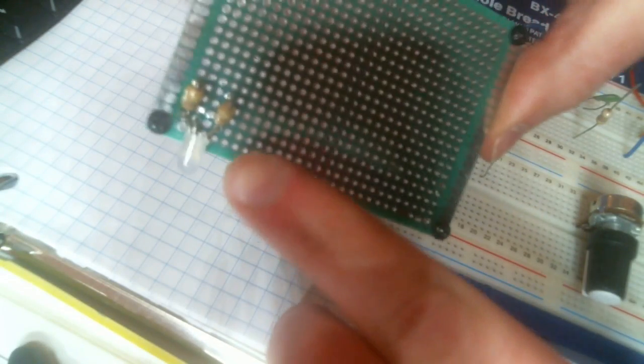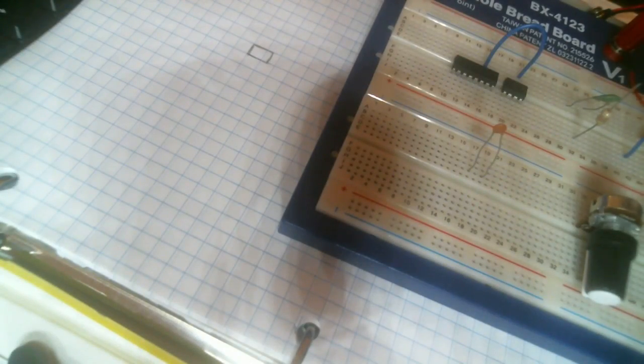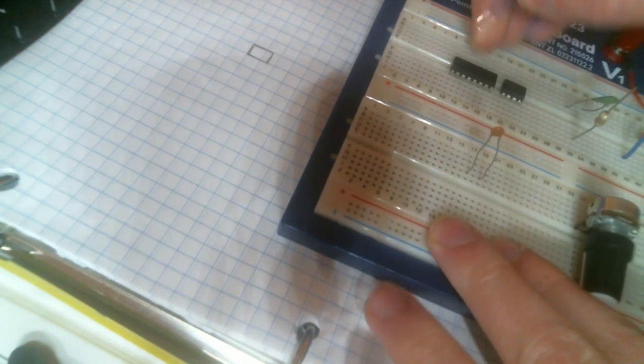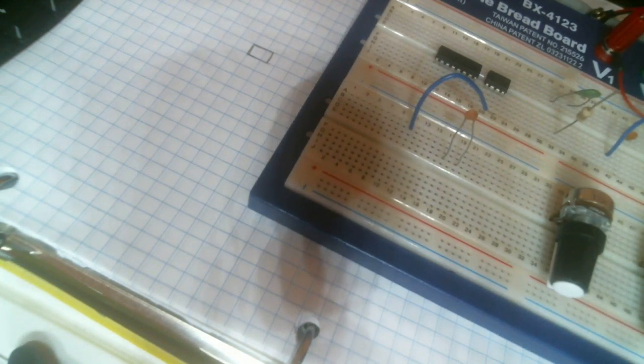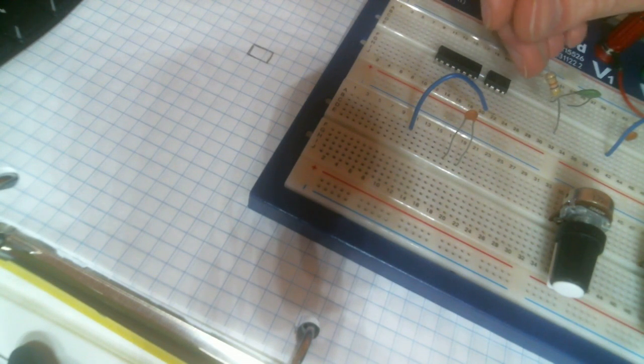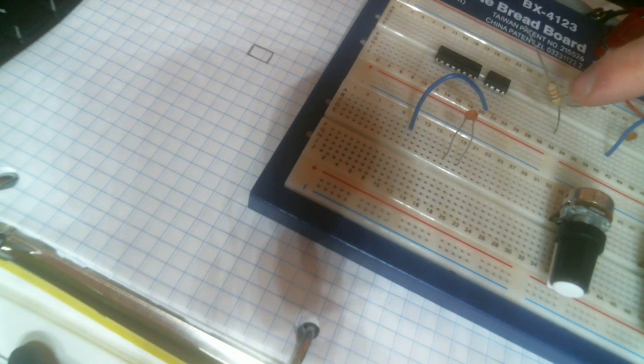Oh, and this is funny. This is an RGB LED where I had to take off the green because I accidentally hit it with 1.9 amps instead of 19 milliamps. Turns out the resistor I picked was yellow, purple, gold, gold instead of yellow, purple, brown, gold. That means it's 4.7 ohms, not 470 ohm. Because LEDs can only take like 20 milliamps. So if you're running it with 9 volts, then you need a 470 to drop it to 19 milliamps. 470 ohm resistor, that is. Like this. Well, this is a 47K. This is yellow, purple, orange.